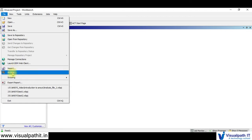Then we have the archive option. The archive option helps us to archive a finished project. There are options with which we can archive with the results from the analysis, or we can clear the results and archive just the main things, like up to the meshing part, and the analysis setup will be archived. These terms, analysis setup and meshing, might be a bit new to you from an Ansys point of view. We will come to them in detail when we go into the detailed course on Ansys Workbench.